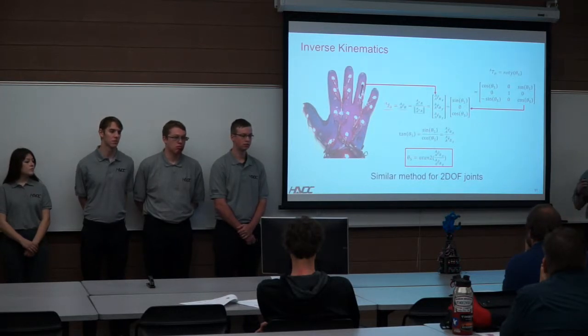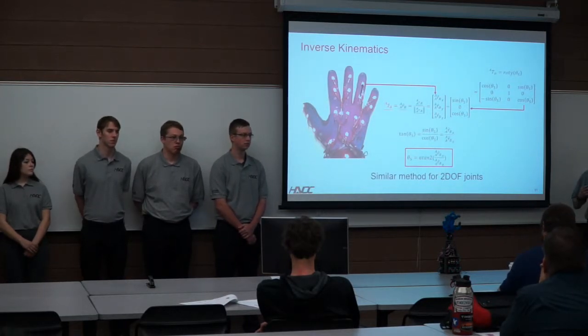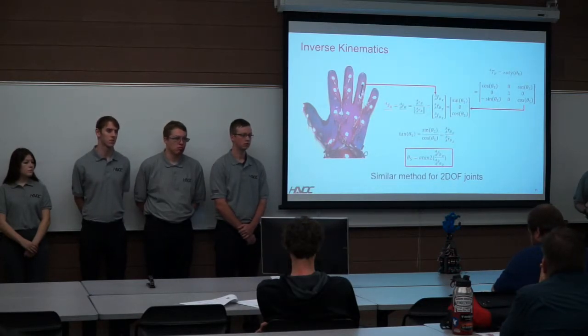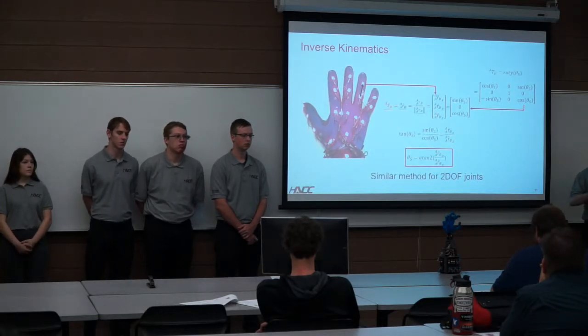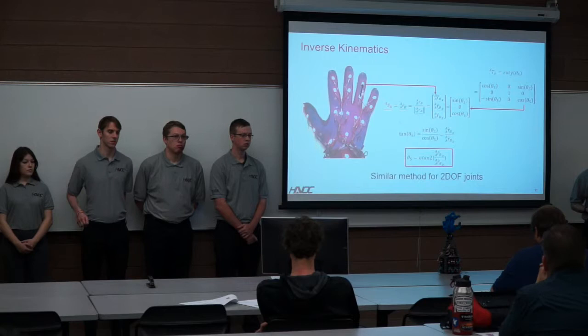To solve for this, the first thing we use is our earlier assumption that all the frames were oriented the same way in their initial position, and the fact that we are using the atan2 function, which has a span of 4 quadrants as opposed to a normal tan's 2 quadrants.